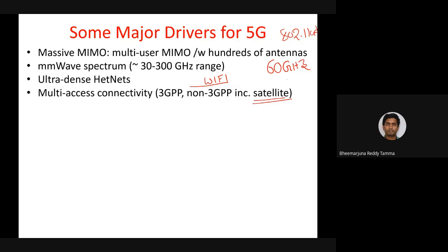For that, when you have satellite, even though it has a longer propagation delay, from satellite to the ground you always have line of sight, and the path loss that you experience from top to bottom will be much less compared to when you transmit in the terrestrial region, because on earth we have a lot of obstacles which eat away the signal.